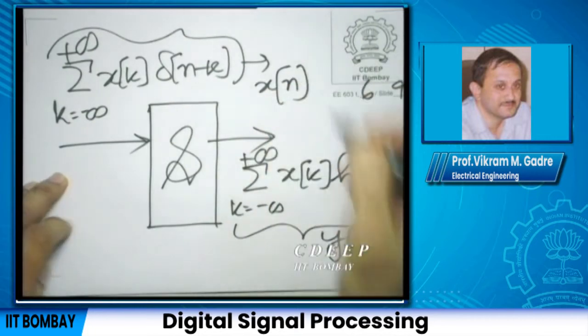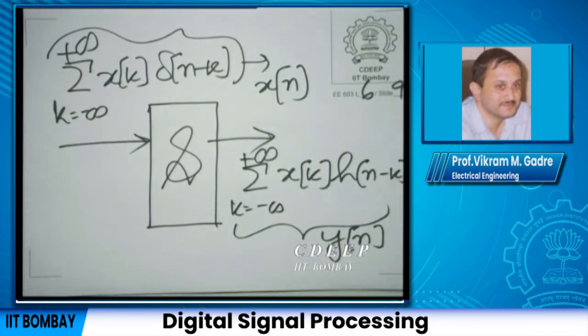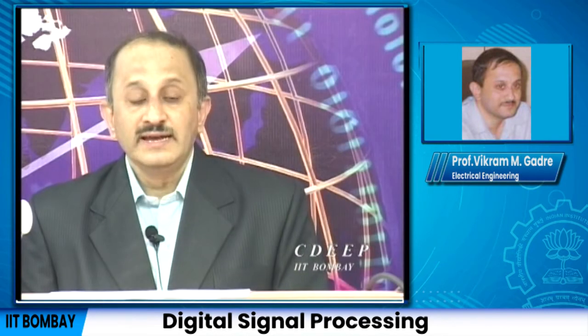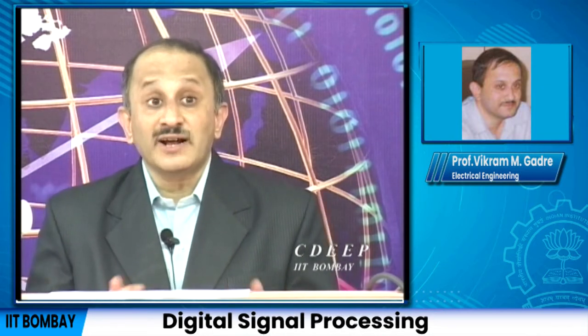And what is significant is that here we have put no restriction on xn at all. For any arbitrary xn that we gave, we have an expression for the output in terms of the impulse response hn and the input xn. So, in fact, not only have we proved the theorem, but we have also given what is called a constructive proof, a constructive as against an existential proof.